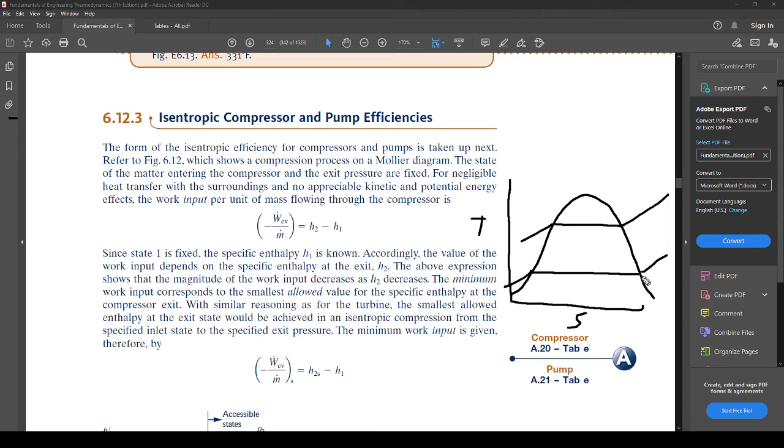So, the compressor, once again, is very similar to a turbine that has blades in there, right? And it's like spinning it up. Or it depends on what type of compressor, I guess. But we're talking about this. This would be state 1. And then state 2 is a straight line up. So this is the inverse. And this would be 2S. And then 2 would be over here somewhere, right? So this right here is how a compressor would look in this class on a TS diagram.